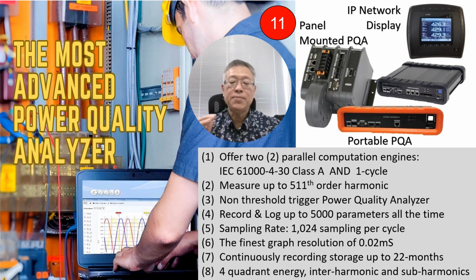It's a non-threshold trigger power quality analyzer, and it can record up to 5,000 electrical parameters simultaneously with a very high sampling rate of 1024 samples per cycle, and it offers the finest graph resolution at 0.02 millisecond. So you're going to have very fine resolution, not 1 second, not 1 minute, not 1 millisecond, but 0.02 millisecond. Continuous recording up to years. Yeah, 2 years, 4 years, it depends which model you choose.